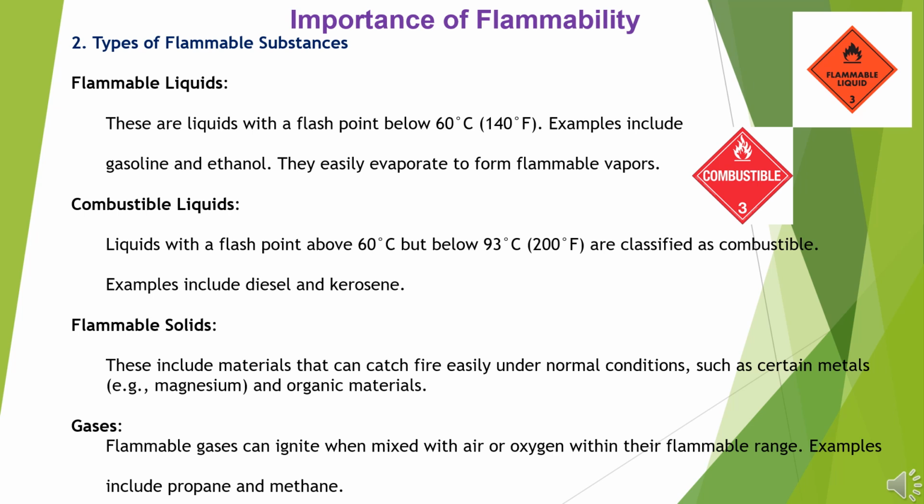Combustible liquids. Liquids with a flash point above 60 degrees Celsius, but below 93 degrees Celsius, 200 degrees Fahrenheit, are classified as combustible. Examples include diesel and kerosene. Flammable solids. These include materials that can catch fire easily under normal conditions, such as certain metals, e.g. magnesium, and organic materials.